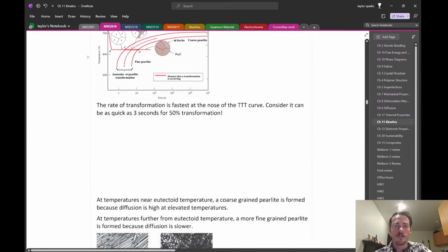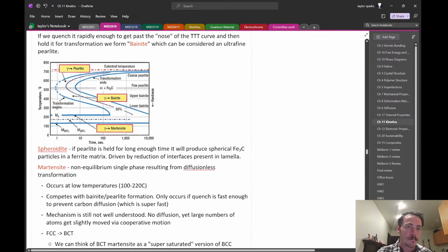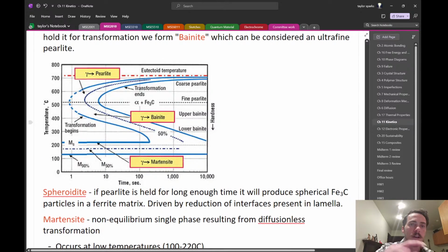So here we show it for a bunch of these different steel ones. Here's the complete steel TTT diagram for eutectoid steel composition, where again, if you can get it from above its eutectoid temperature at around 727 C, if you can cool it all the way down below this nose, 500, if you can drop it over like 250 degrees in less than a second, that's not trivial always, then you can avoid the beginning of the transformation to either pearlite or bainite.